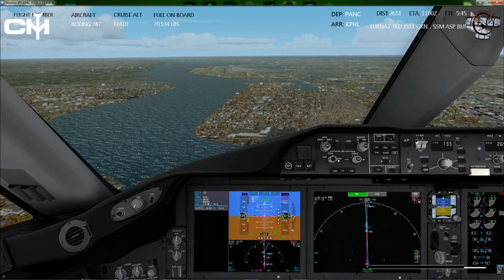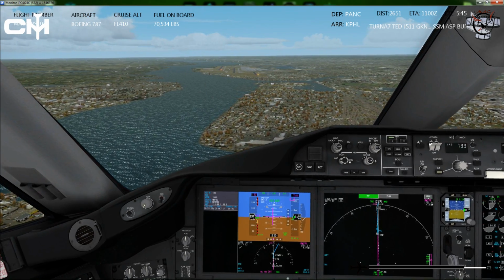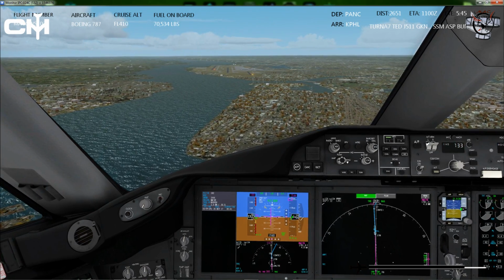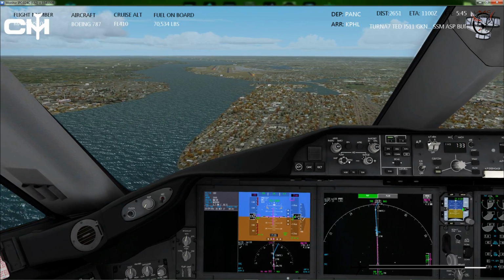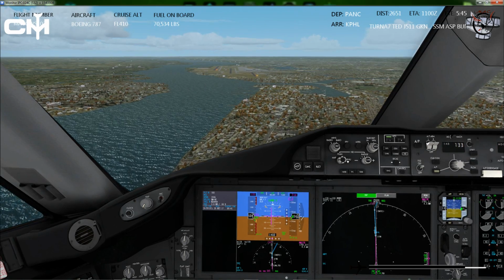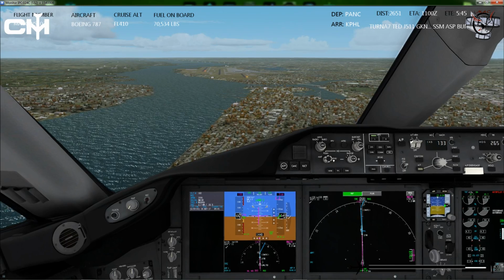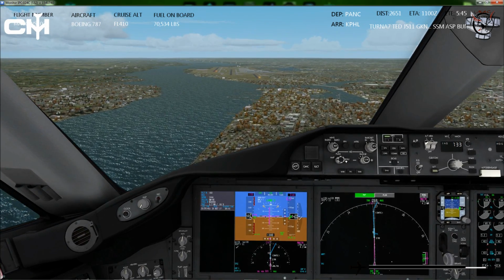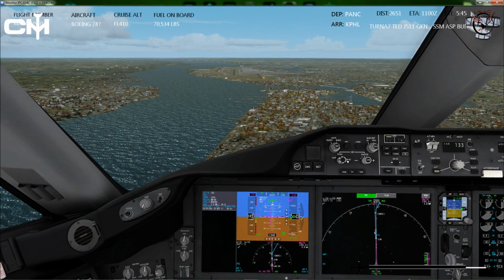And so we'll use the trim to adjust our rate of descent. This is one nice thing about Track IR: I can look straight down the runway even though we're off to the side, even though the nose is pointed to the right. We got a 12 knot crosswind where we're at right now. Landing checklist. Gear is down, flaps are down, and what was the other one on there? Oh, speed brake set. Is it? Yes, it is. Speed brake is armed. That's what we're looking for.